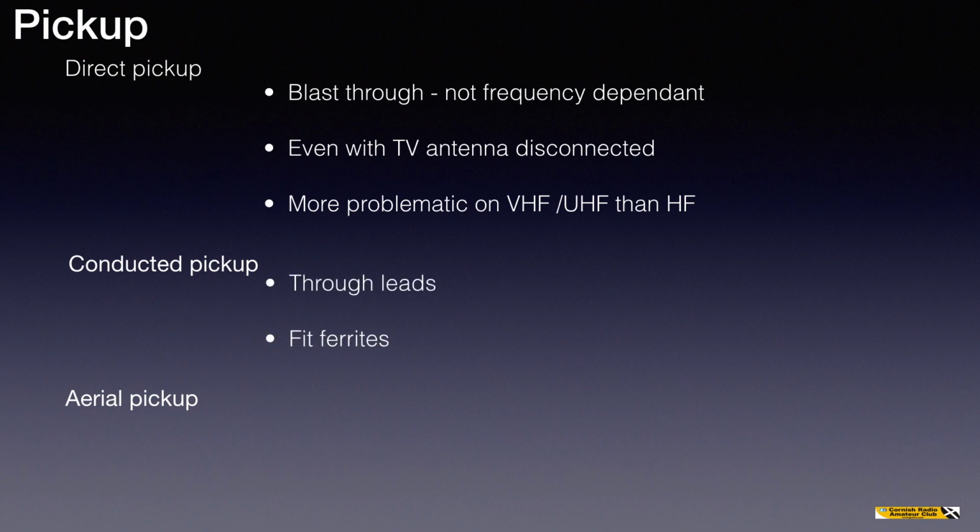Conducted pickup comes in through the leads, and you can fit ferrites. You can also fit ferrites to signal leads, and the same logic applies, in as much as it tends to allow the low frequency audio signals through, but attenuate the RF signals that are picked up by those leads.